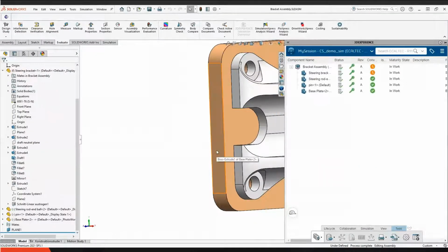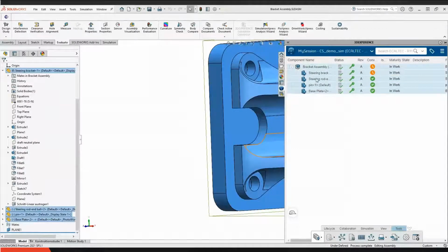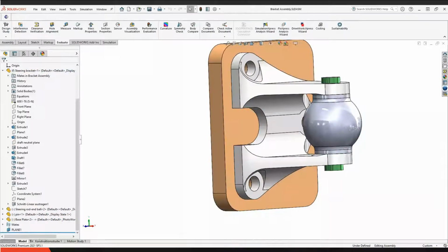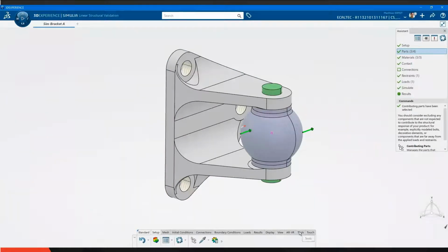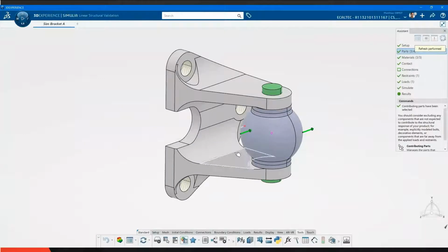So it updates the original files with the new ones. The revision control of the PLM system is great. So it's done, it's been re-uploaded. Now if you go to the actual simulation that you ran and you show the body, you do a refresh and it'll bring up that cut in the bracket. So you'll see, yeah, it has a little cut, cool, now the part's changed.